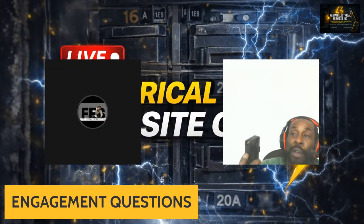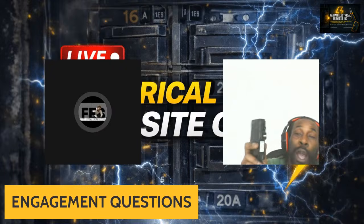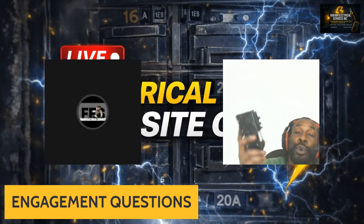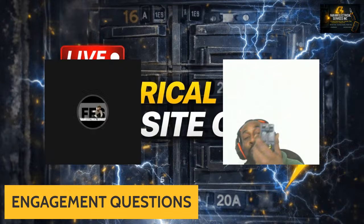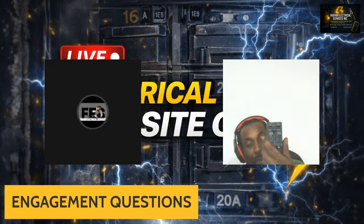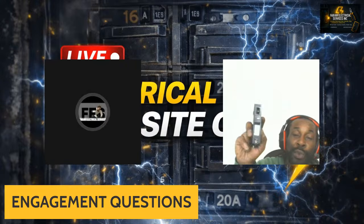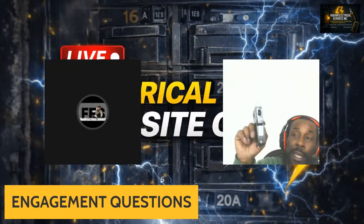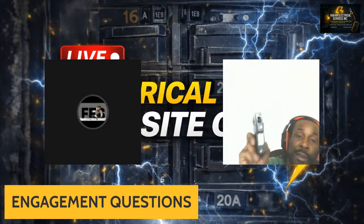So it's very important that you protect the wire itself. The proper size wire for this will be a 12-2 wire and not a 14 gauge wire. Again, this is where you would use your 14-2 wire, on this 15 amp circuit, which will give you basically a 15 amp breaker, 15 amps of power.